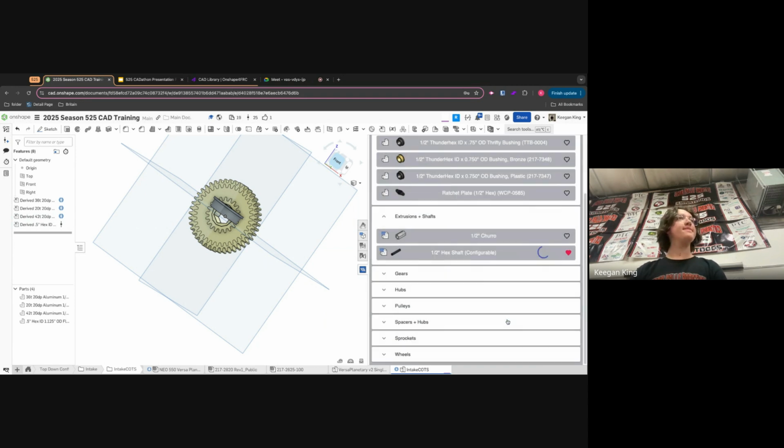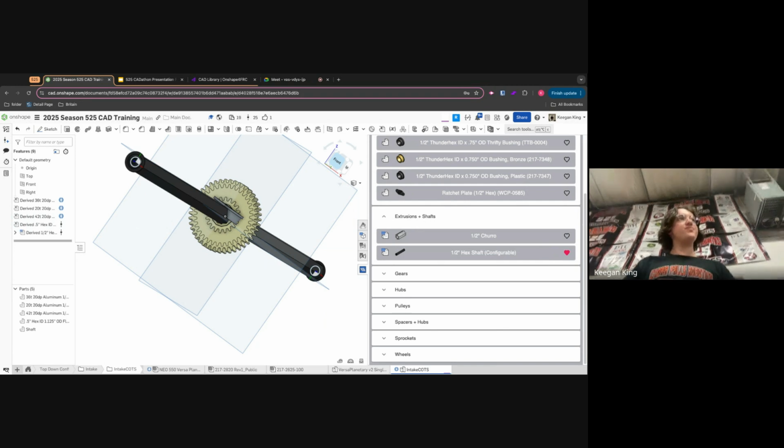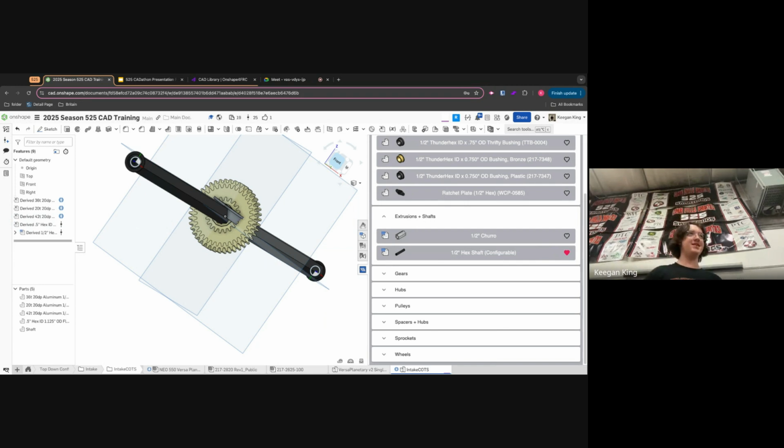You made this 18.5 inches long. Yeah, because it has to extend past. But it's 18 inches between the 2 plates. That's on the inside face. It then has to go past some bearings. And that's the inside of the bearings, which the bearings are each 1/4 of an inch thick. And actually, it's based off what is actually on the robot. There is purpose to that measurement.